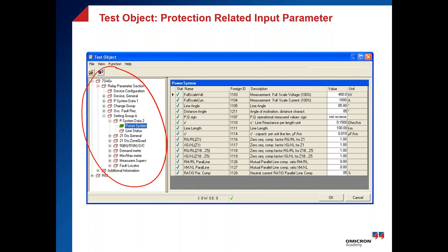This helps you a lot, because, for example, if you have feeder number 1, and everything is the same in feeder number 2, but there is just a small change. For example, trip time on zone 1 here is 0 millisecond, there is 20 millisecond. You don't need to export and import again. Just go to the second feeder, change the trip time of zone 2, or for zone 1, and run the test, and the test will succeed. We just make it for simplicity.